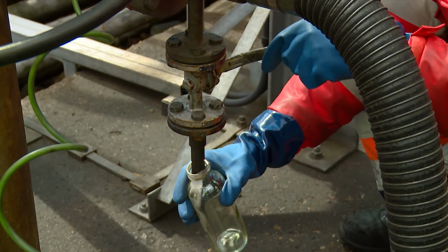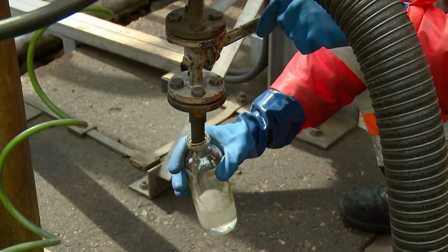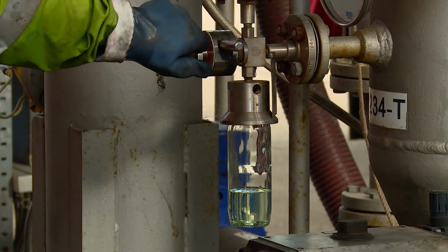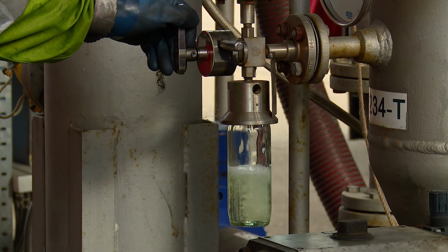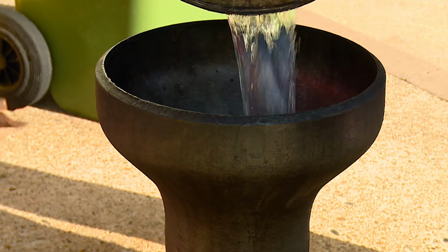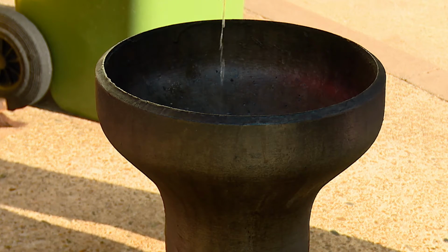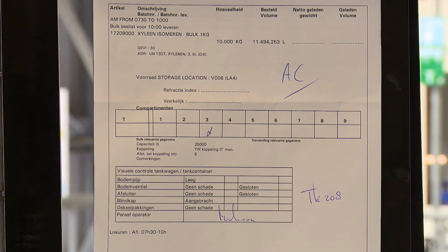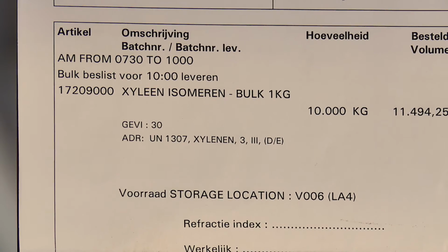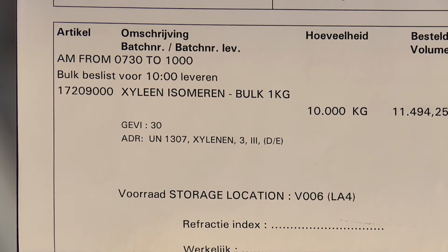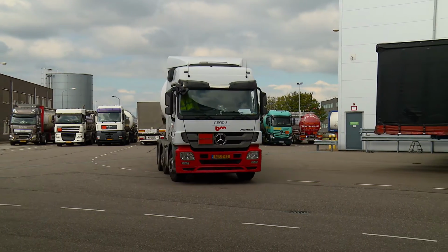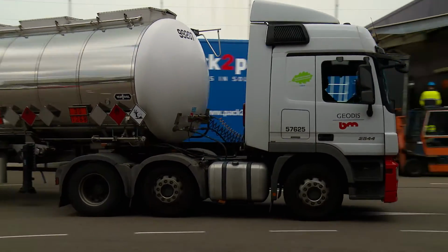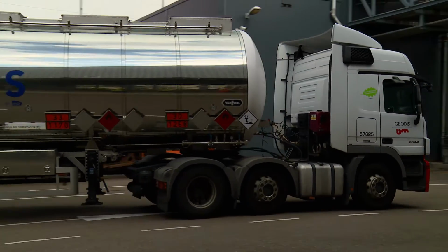If samples are required, these should be taken from the bottom valve if possible or according to agreed site procedures. It is important that no loss of containment of solvent occurs during the sampling process, and spillages must be contained and reported. Some sites do not require samples and will issue a certificate of analysis or conformity for the customer for bulk deliveries. Samples are transported on the vehicle in an approved sample carrier in accordance with ADR regulations and are not to be carried in the vehicle cab.